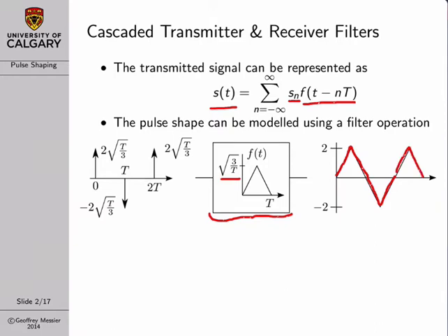In order to produce this transmitted pulse train waveform, at the input we pass in a series of impulses, and each impulse has a weight equal to the signal vector value. Again, remember these are weights and not amplitudes, because these are ideal delta functions that have 0 width, infinite height, and an area of 1.